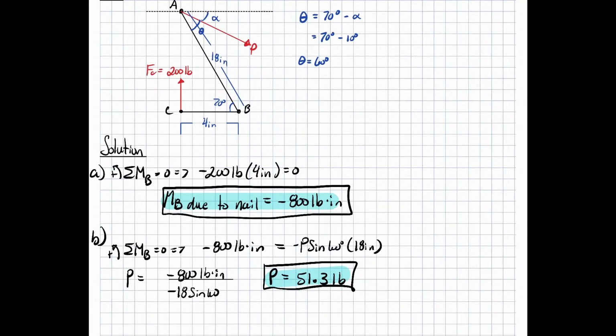Okay, we got a question here. Can we just always put the moments as counterclockwise and have our answer indicate whether that is correct or not? Or do we need to conceptualize and take the time assuming it? No, so the basic assumption for a moment is counterclockwise positive. Most engineering aspects in the real world, they associate counterclockwise as positive. That is why I'm stating it positive.